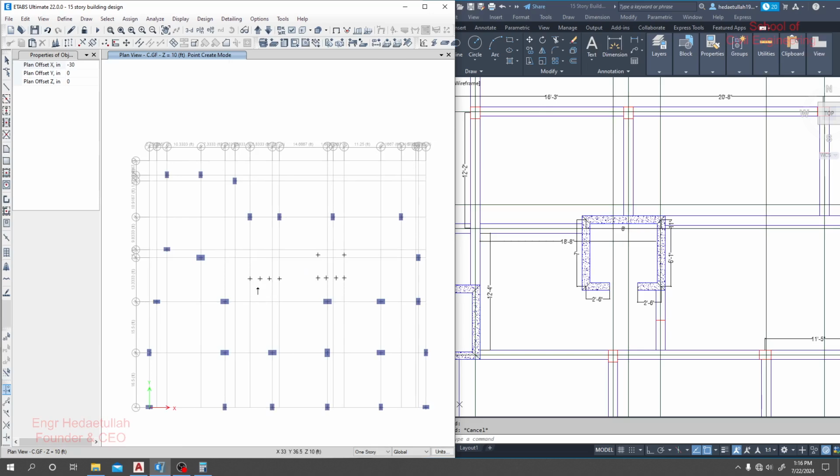Done. Now we are ready to draw our shear wall. To draw a shear wall, I will use that option. And here the wall preliminary I have taken as 10 inch. Maybe we need to change its thickness later, so we'll do it later. And we must stop that auto mesh or expander option.